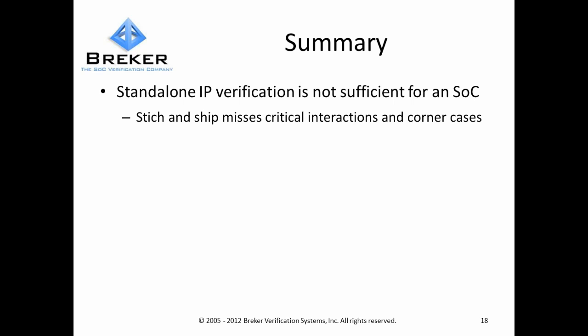So in summary, SoC verification, stitch and ship does not work. Verifying individual IPs does not mean that your entire system works. There are many points of convergence across IPs: on the buses, on the memories, on interrupts, on sideband signals between the IPs, on IOs, on power management. These all have to be tested at the system level.